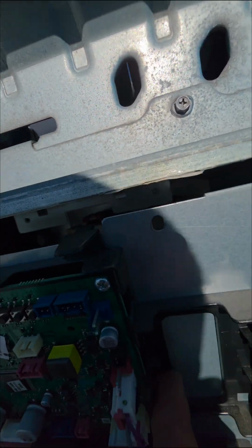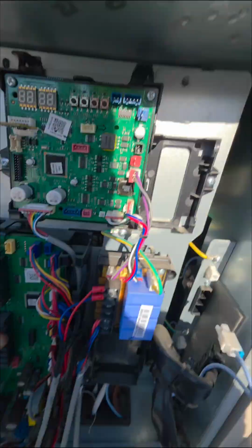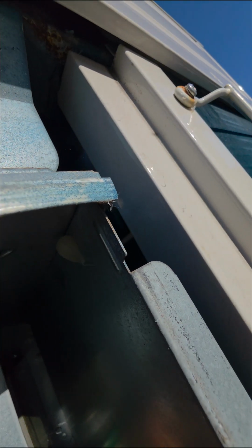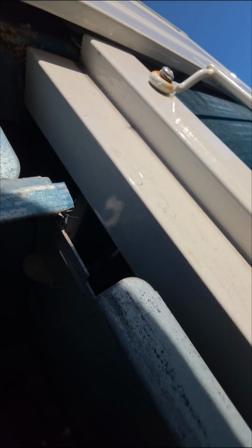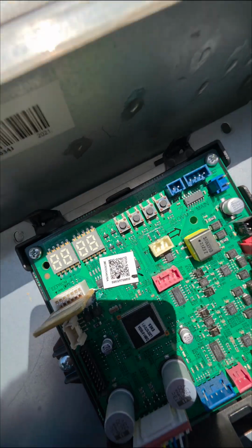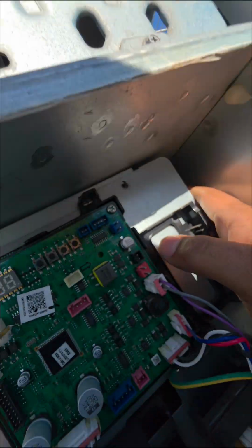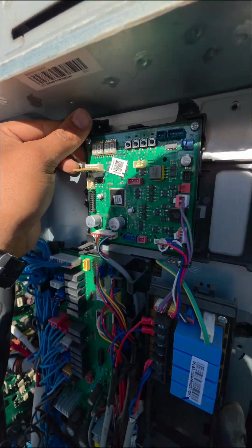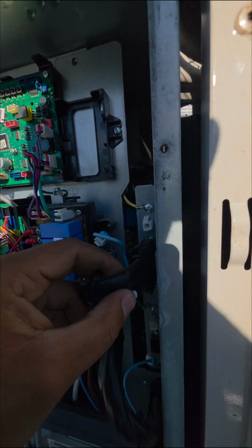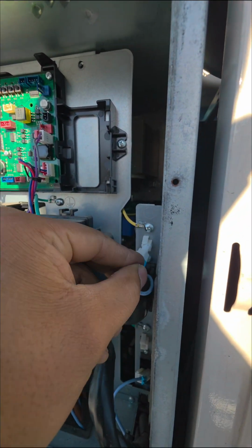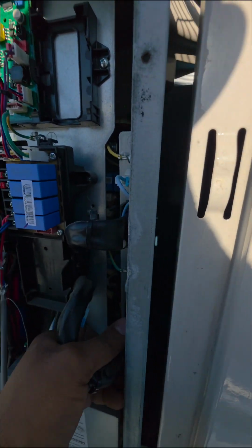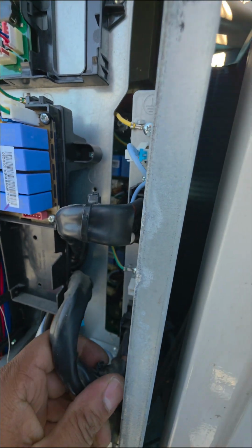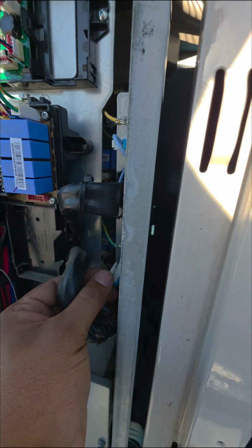Anyway, so now we will clip this guy in, and it's a little bit difficult to do it with one hand. We gotta lift and get it in there. So these two top clips, there we go, need to be in place, and then screw them down. Okay, then we can go ahead and insert these. And this is your neutral over here, which is essentially for your single phase controls.